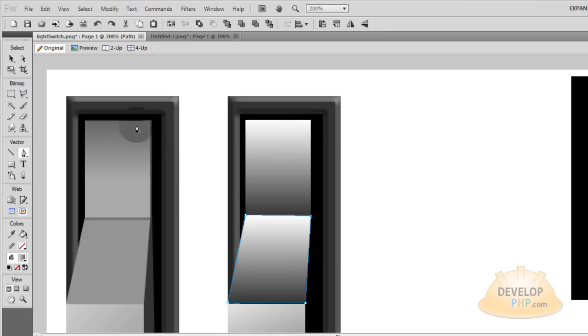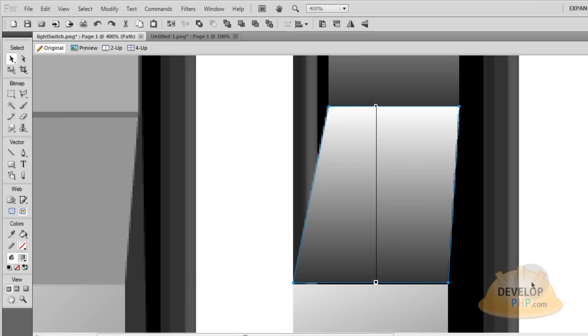Or in my case, my line is jagged, so I can move that point, that selection, just that point up to make sure that line is straight. Now this, you can see, is not all the way in the bottom. So I can grab the sub selection tool, grab that point and that point by holding shift while I grab them together and move them both down simultaneously.